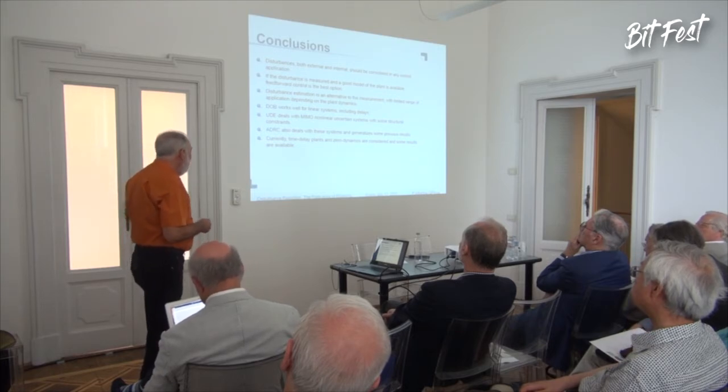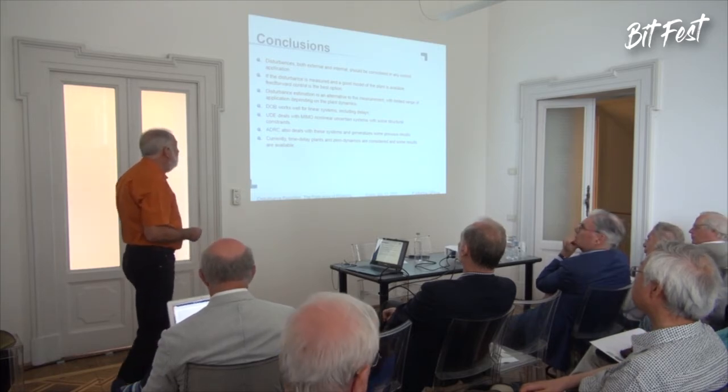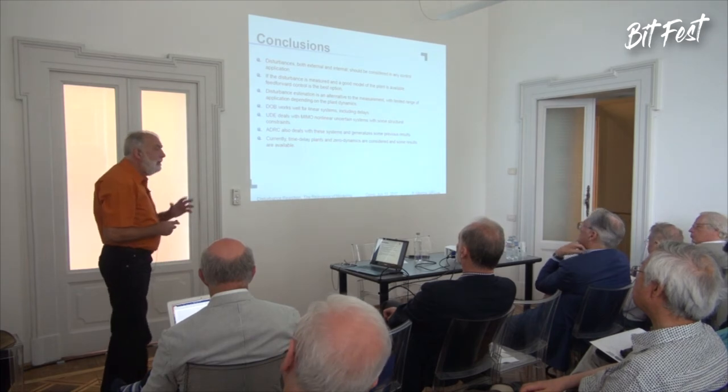Also, two open questions for me are: what is the robustness of the ADRC and the EUDE with respect to the uncertainty in the model, and what is the relationship between the filters Q, GF, and the Luenberger observer in the last design. But in any case, we think that we should try to estimate the disturbances and try to reject them if possible.